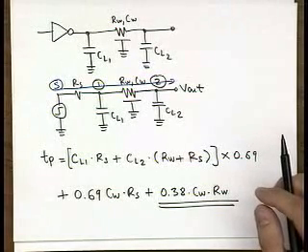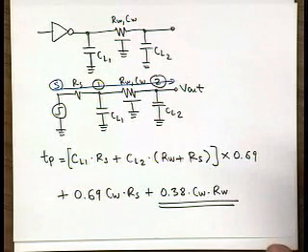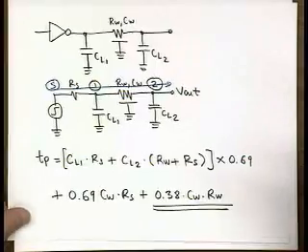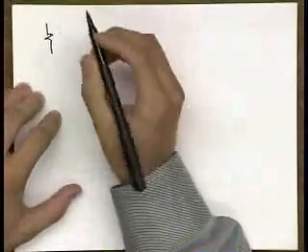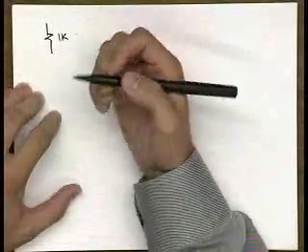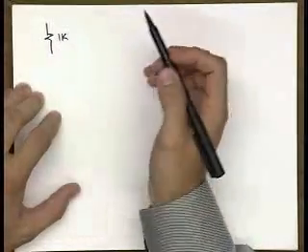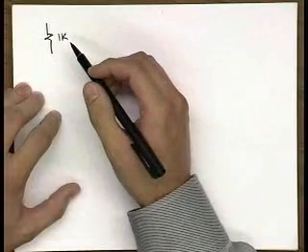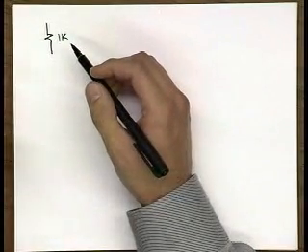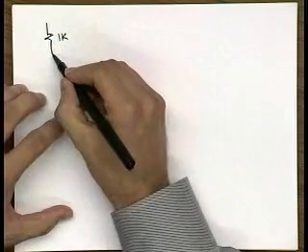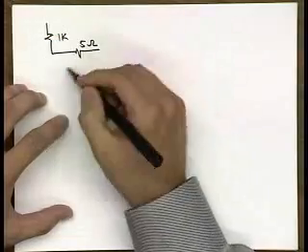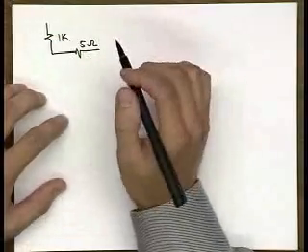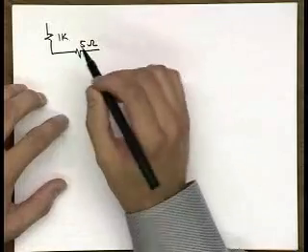Shall you go with a distributed model that's more complicated, or just make use of the lumped model and your analysis is still accurate? So when you have a scenario where your source resistance is, for example, in the kilo ohm range, which is a realistic value from the analysis we did a couple lectures back for the equivalent resistance of a transistor, and let's assume you have a very tiny wire, say a 5 ohm wire, then you just ignore the wire, because that resistance is so significantly smaller than the source resistance.